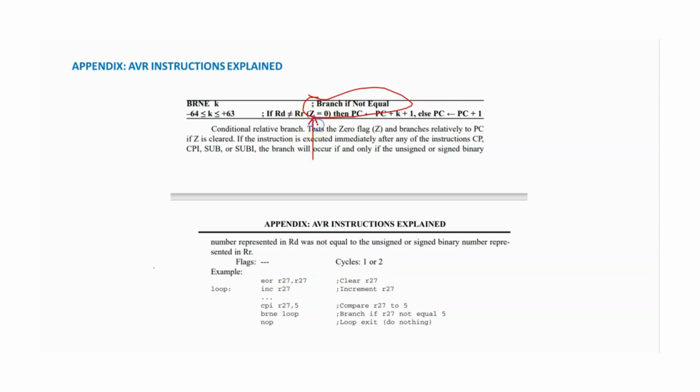The status register has different flag bits of different types. One was the carry flag bit. No, it is the 0 flag bit. This instruction is also a conditional relative branch, or relative conditional jump instruction, and it jumps if the 0 flag has 0 value. Otherwise, it will not jump, it will execute the next instruction.